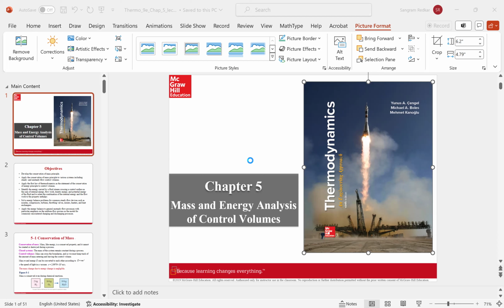Now, the mass balance for the steady flow process. Please understand, in this problem, we are not allowing any mass accumulation, which means whatever mass is coming in, the same amount of mass is going out. So in this case, there are 2 inlets. Mass coming in is 2 kilograms per second. Mass coming in is 3 kilograms per second. If you do not want mass to accumulate inside this control volume, the mass going out has to be 5 kilograms per second. And believe it or not, these principles are universal.